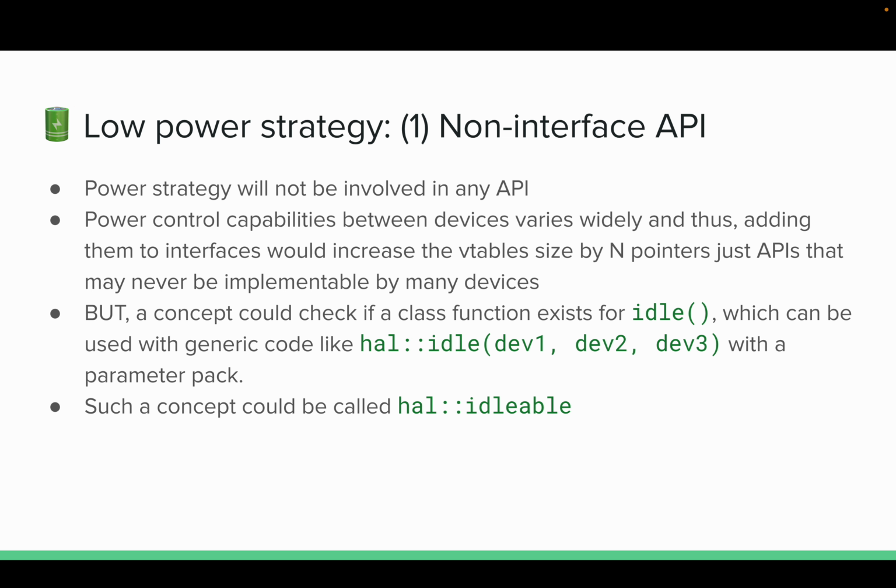But the other idea here is that a concept could check if a class function exists for idle. So for example, you could write generic code such as how idle, give it a whole bunch of your drivers, and then it will figure out how to call all of your idle functions. It'll say, oh, parameter pack, here's all the different types that were passed into the function. Here's how we call all the APIs. The concept can be called something like idleable or shutdownable or deep sleepable, something like that.